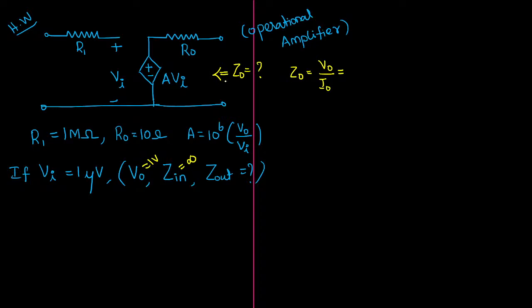But what you must think here is, listen, in the first part of the circuit, if you observe the first part of the circuit, basically when I was trying to calculate the input impedance, did they give any source here? In the first half of the circuit, there is no relation between the first half and the second half. So while calculating the input impedance, I considered only the first half directly. Similarly, when you consider the second half, how will you calculate the value of input impedance in the second half? That is the next question.